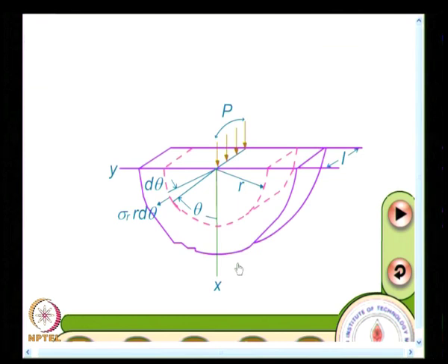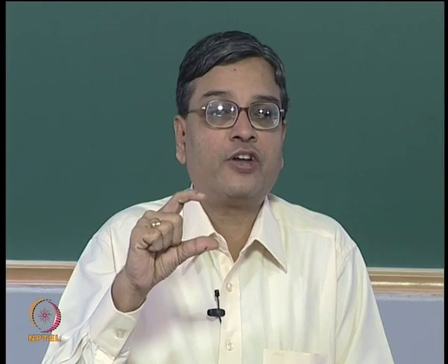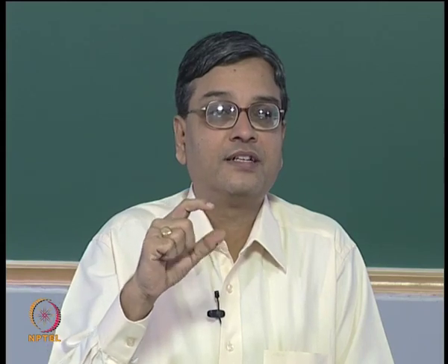And if you look at the concentrated load, this is like your Boussinesq problem. Then you have extension of this. If you look at the contact stress analysis, it all started from this basic solution of Boussinesq, which is extended by Hertz, and you have the Hertzian contact problem. And we have also looked at how to find the solution for a disk under diametral compression. That also comes from this basic solution. So, it is a very useful solution,